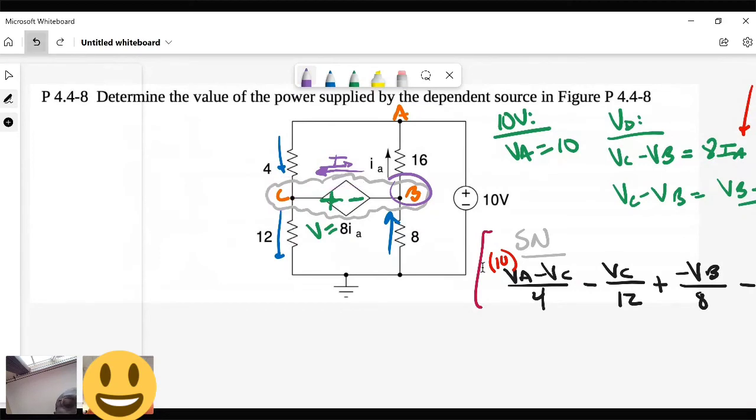That's a voltage way of thinking. But I like the track that you're on because it's similar to the current. All you have to do, if you don't know the equation for the element in itself, the only thing you can do is solve for the current using a regular old traditional KCL. And so that means you can do it at C or you can do it at B because the current going from B to C is ID.